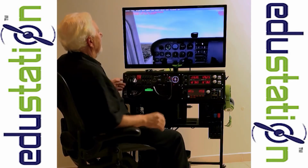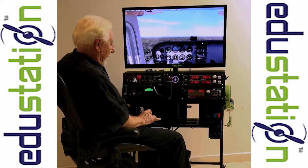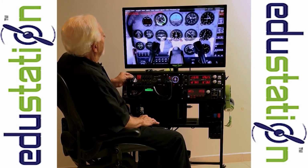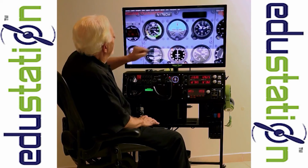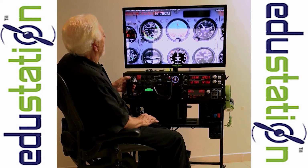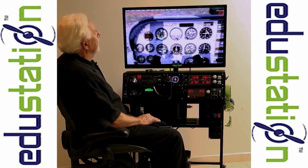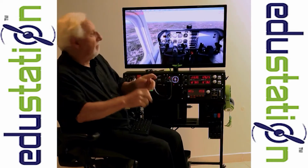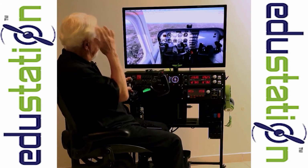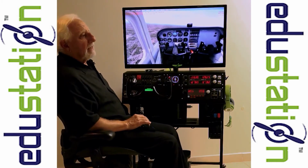And now we're going to come back into the cockpit. I'm going to show you something else. Remember we talked earlier about covering the white line with the orange? So if you look carefully here, I'm going to trim the plane so that we fly with the orange over the white line, right there. And we use this in the airplane so we don't have to hold on for dear life. We get the plane trimmed out to where we would like it, and we let the plane fly its course.